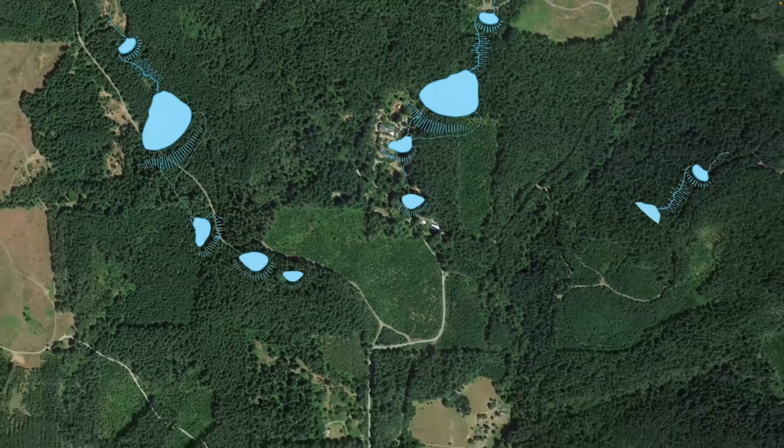It basically skims surplus water and moves it via a pipe around the dam and puts it back into the channel. The trickle tube can be installed at the same time as the spillway is built in connection to the dam. And it usually wants to just run right through the edge of the spillway and out. You would basically be wanting to have a tube that's big enough to accommodate your seasonal flow.